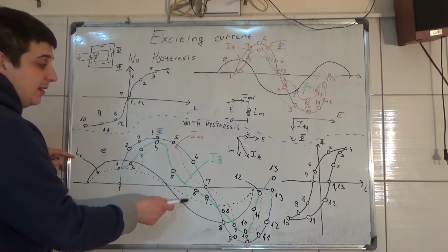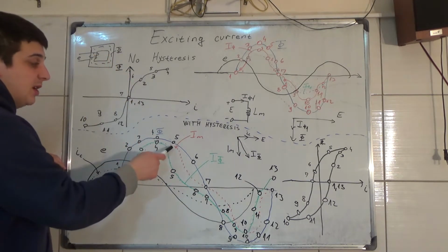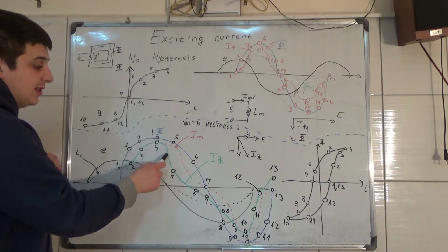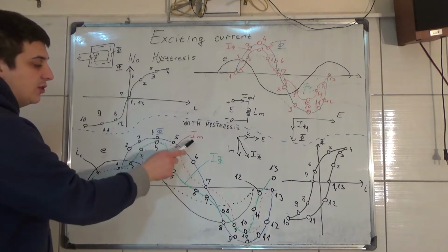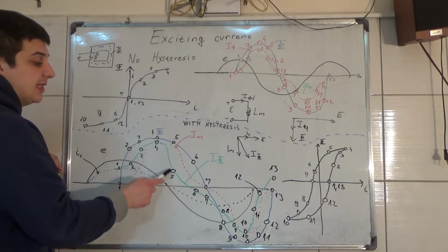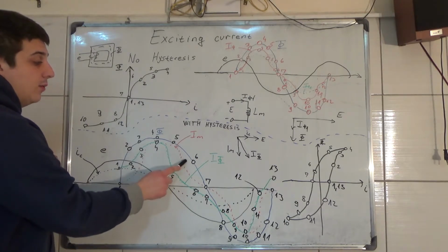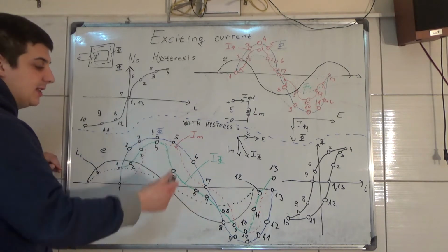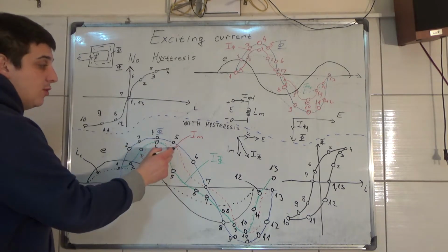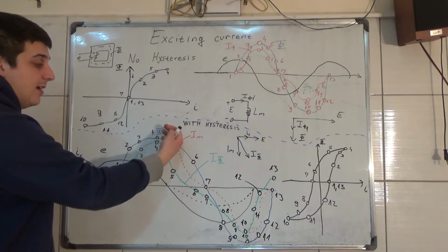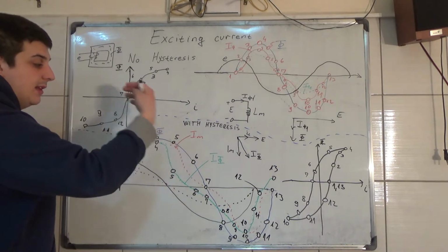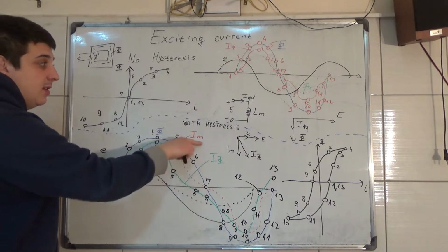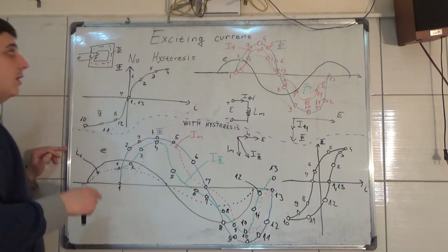Now, as you can see, because this IC is now negative, it subtracts from this IM. You can see that this exciting current decreases here, not with this IM, because this now has a negative value, and when you add this and this, you will have a curvature that is falling lower and faster than the magnetizing current of this coil.